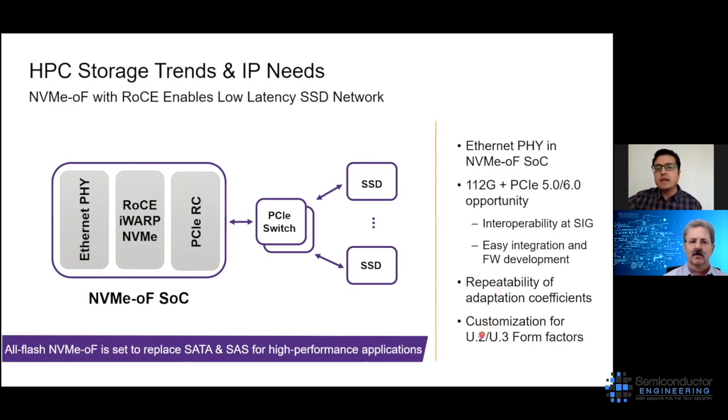Finally, SSDs come up with a new form factor. Solid state drives very rarely use the PCIe form factor. They use U.2 and U.3. And there are a lot of customizations with the SerDes PHY implementation which are needed in terms of digital implementation to support this U.2 and U.3. So this requirement was never there for Ethernet PHY, but these new designs are asking the 112 gig PHY also to support U.2, U.3. So these are new requirements with respect to SSD applications with hyperscale data centers.